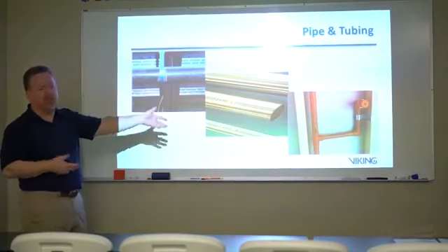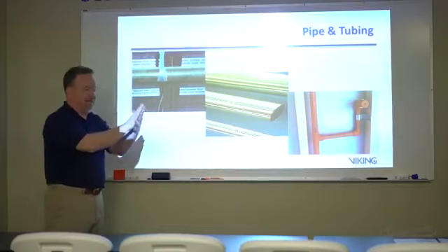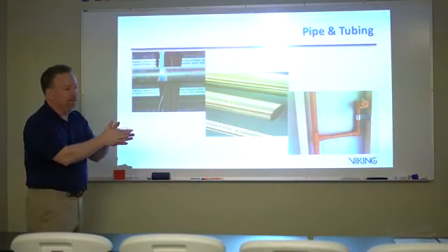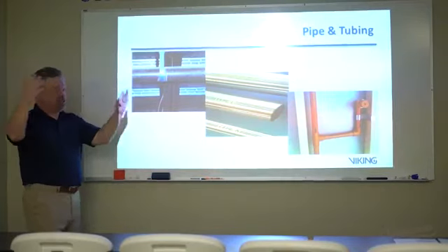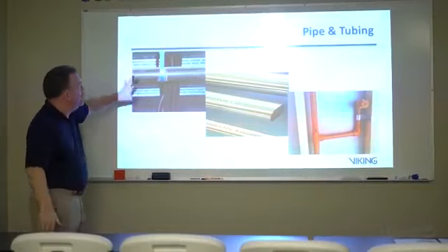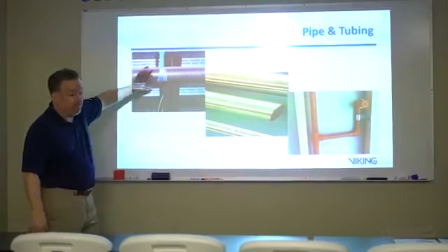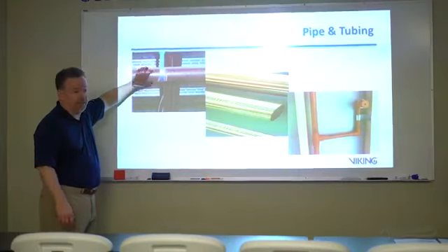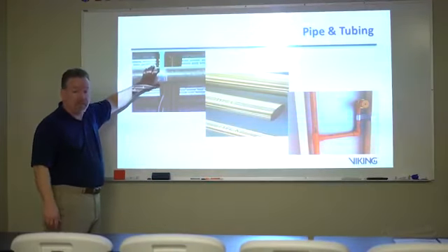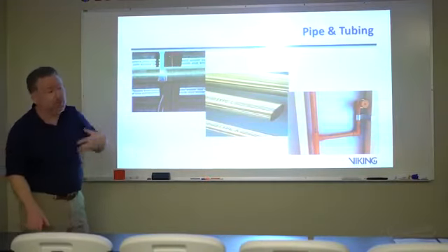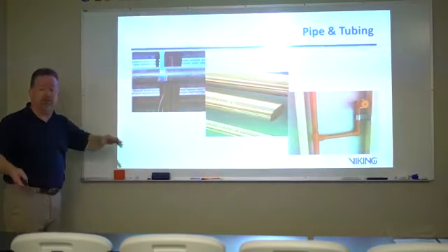In many cases, it's got to be placed behind walls. It's not listed to be exposed in some cases. In some cases it is, depending on where you go. So steel pipe becomes the least expensive, most prevalent, but we have to be careful of its friction loss. So using the calculations, we've got to make sure we have enough water.